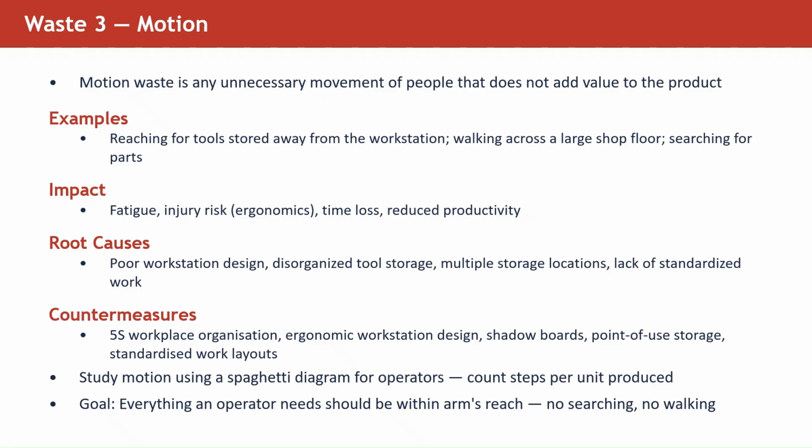For example, let us say an operator walks 200 meters more than necessary per part, and you are producing 400 parts per day. If you multiply 400 by 200 meters, the amount that is piled up is around 80 kilometers of wasted walking per day, and that happens every day.